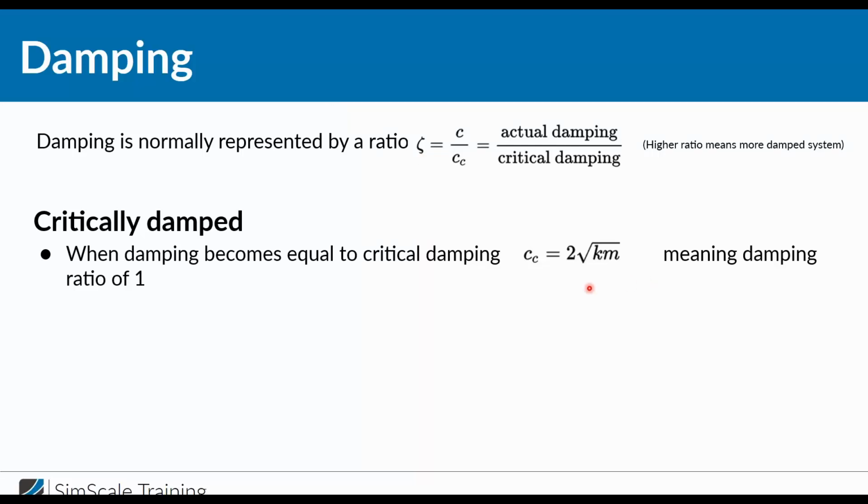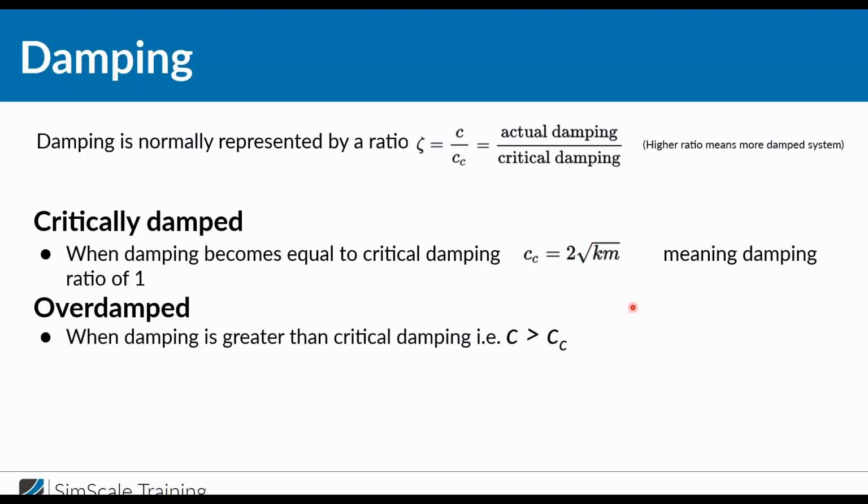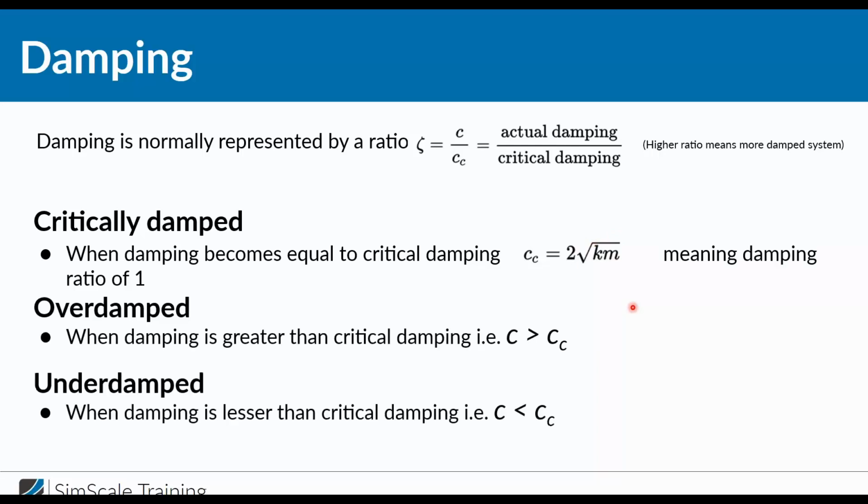If you take a look at how to calculate this critical damping, you might see this formula. In a lot of textbooks, especially at universities and colleges, if you talk about vibrations, there is this example based on a pendulum, or this example based on a spring, a damper, and a mass, and there you also get a similar formula like that. In this formula you have stiffness and the mass included, and overdamped means the ratio is higher, and underdamped means it is lower. But what does it actually mean?